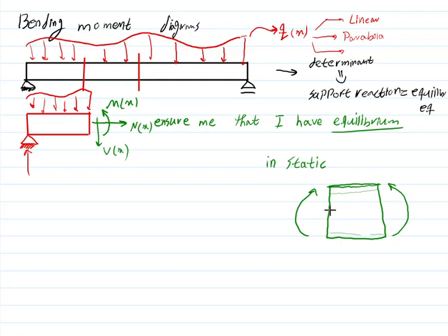But what about the shear forces? The shear forces are the same. Now, why do we make it like that? Because you see, if I try to get a moment equilibrium around this support, the shear force must be able to cancel out the moment, okay?